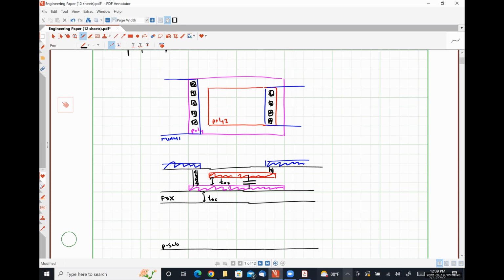Okay, so the picture's a little bit busy, but we have an intended capacitor here between our poly 2 layer and our poly layer. And then we also have a parasitic capacitance here between our poly 1 layer and the substrate. And this is discounting the parasitic capacitances we are going to see between the metal layers and the substrate and things like that as well. Okay.